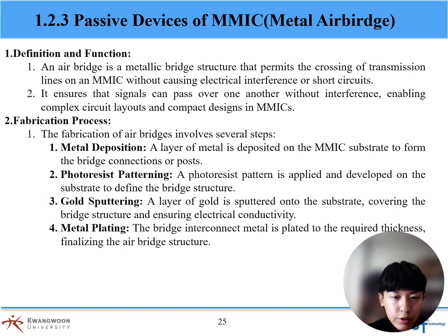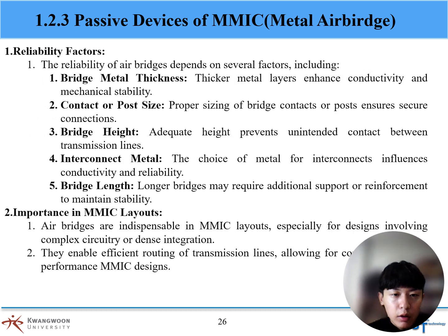The fabrication of air bridges involves several steps. First is metal deposition. The second is photoresist patterning. The third is gold sputtering. The last one is metal plating. And the reliability of air bridges depends on several factors including bridge metal thickness, contact or post size, bridge height, interconnect metal, and bridge length.